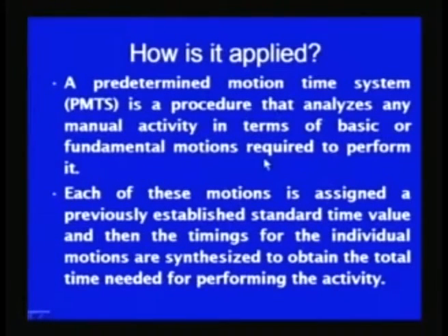For applying the PTS systems, the given job which is to be analyzed and for which time is to be obtained is broken down into a number of basic human motions, so that the time values for those basic human motions can be obtained from the data banks of the PTS systems.